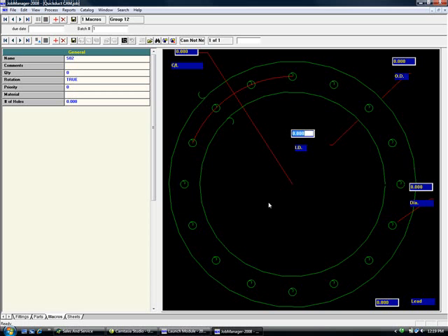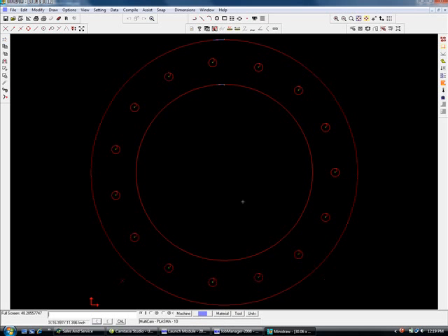You just simply enter in dimension, make an 1/8 of an inch lead in. I'll make one of those, same material, and I'll put 15 holes going all the way around it. I'll save it, 2D view, and this is what we just created.